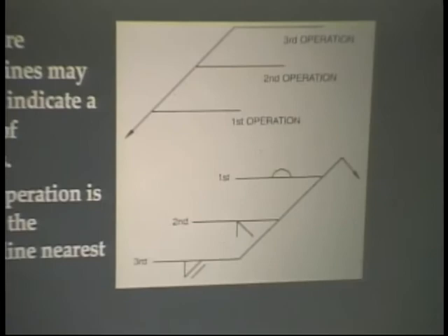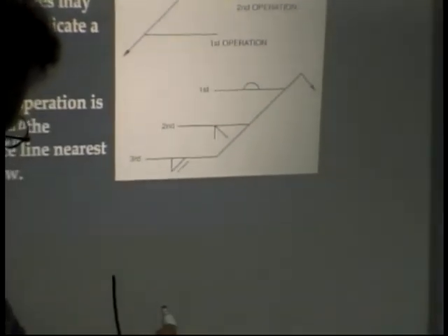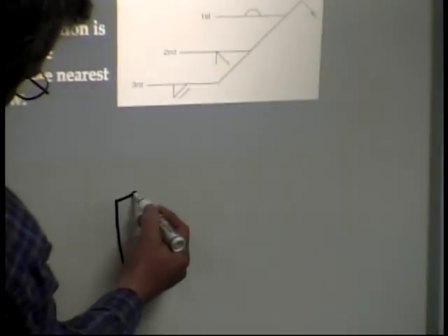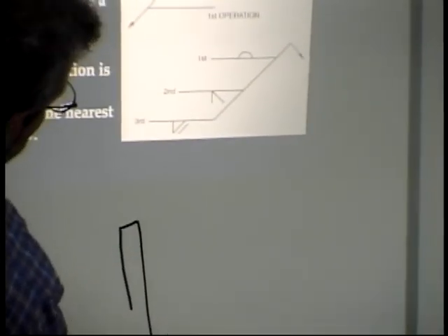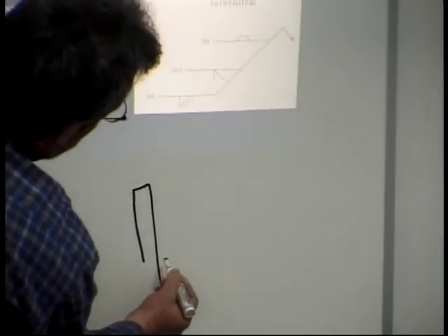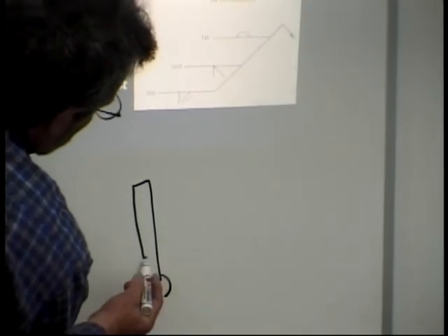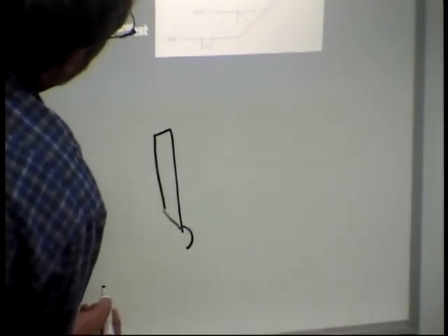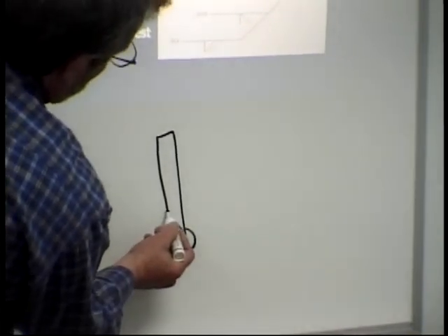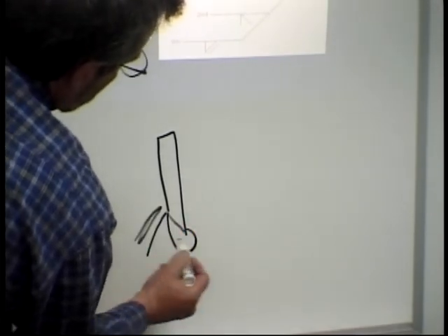Okay, and of course we have the arrow which shows us where it's going to break at. That's going to be on the other side. So we're going to have a back weld here, and then a single bevel here, and then we're going to put a fillet weld out on top of it like that, and finish that thing flat.